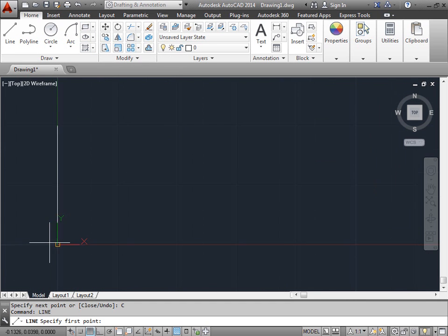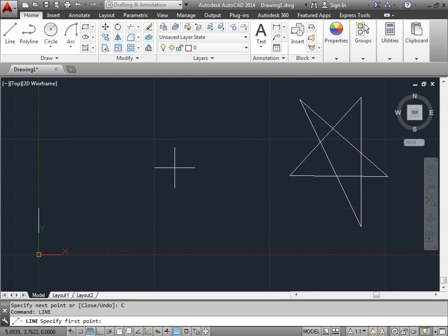Now instead of zooming in and making sure I'm at 0, 0, or turning on any of my other snap modes, we'll go ahead and specify the point directly. I'll go ahead and pan a little bit so that you can have more of the view. We'll click into the command line, and this way we're going to enter 0, 0 and enter. And as you can see, I specified a point in the drawing area without having to click. This method can be very useful if you know the coordinates of where your lines or other geometry should lie.